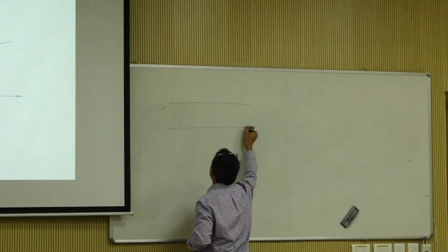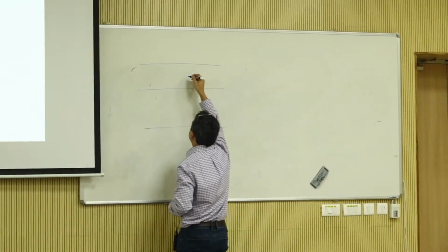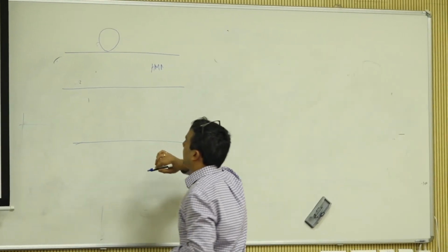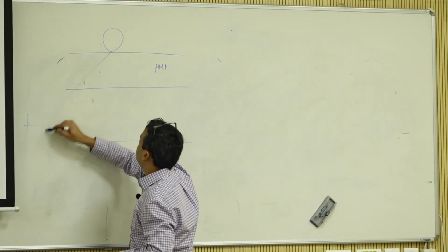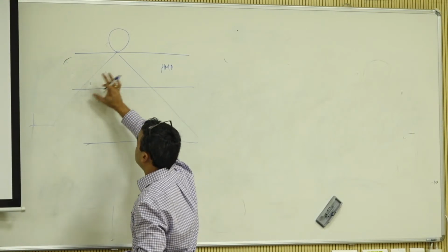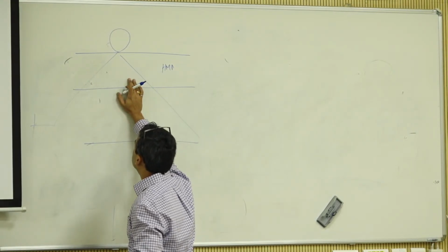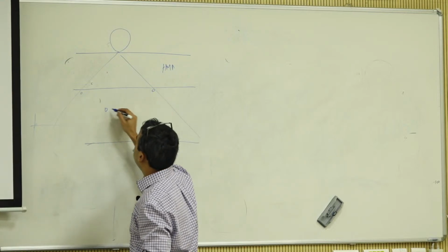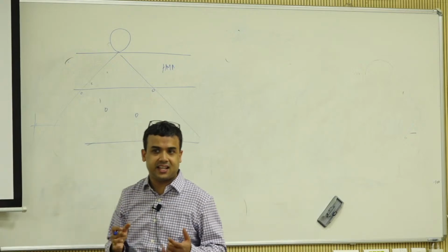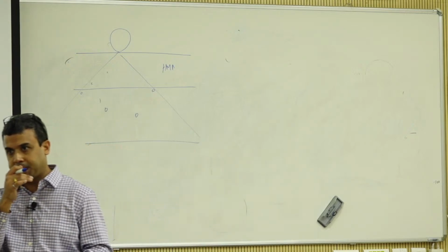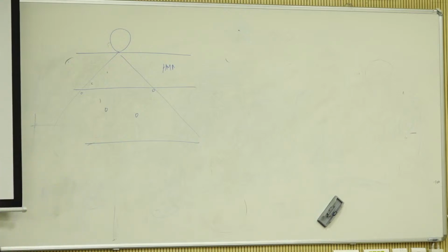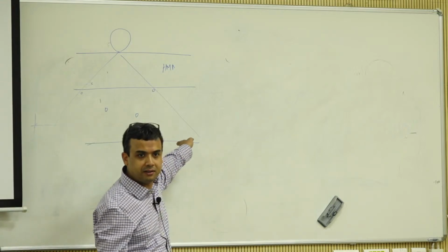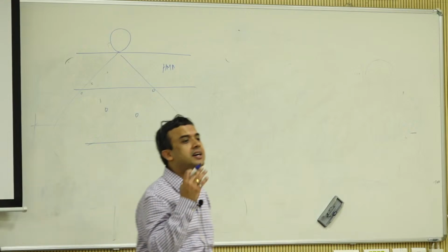In your traditional pavement design, let us say this is your HMA and this is your load, right? And then the stress is being dissipated like this. Yes, the slope will change at the interface, but I'm ignoring that in this case. So you know that between this point and this point, and this point and this point, the stress is different, right? When the stress is different, that actually means that your modulus is also different. It is a stress dependent material.